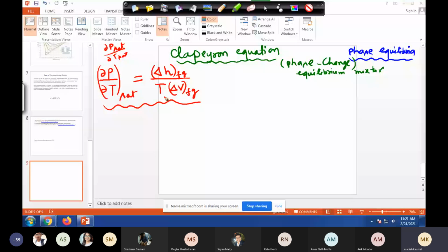One can verify whether this Clapeyron equation works, because you know, for every pressure you know a T sat, or the other way also. For every temperature you know P sat, P saturation. So you can check how well this Clapeyron model can predict the data which is given in the steam table, because the steam table we have prepared from experiments.